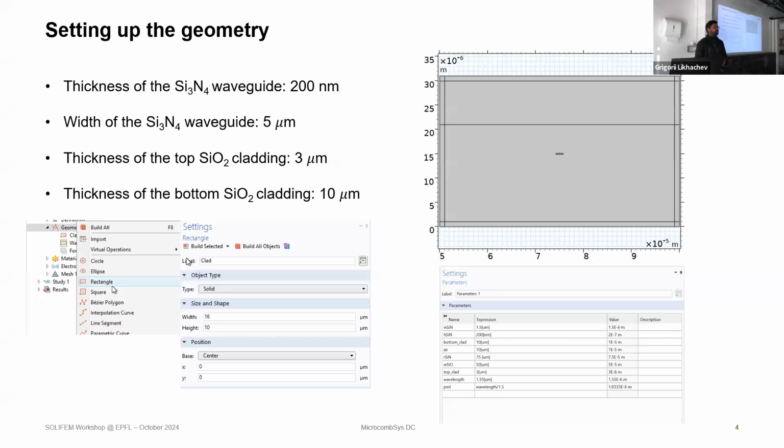This is in order to estimate the bending loss, or, if you want, the cutoff bending radius. Someone may ask what the minimum bending radius is that you can design on a 200 nanometer thin platform, below which you won't find any more guiding. So you have a cutoff bending radius; you cannot make it smaller than this. The whole idea of photonic integration is to make smaller devices, so it is important to know the minimum radius you can design.